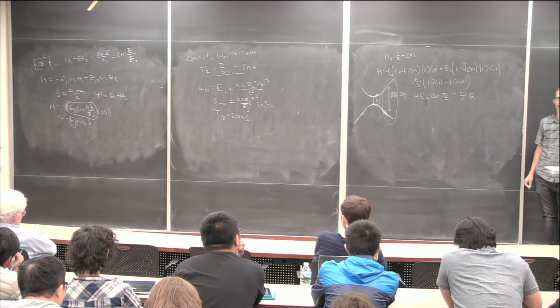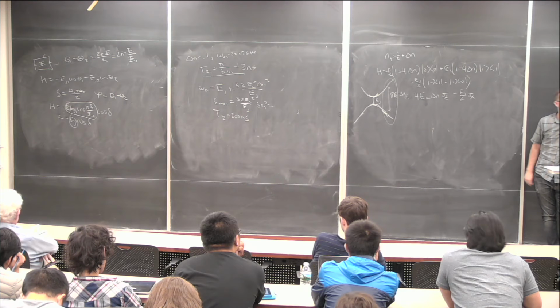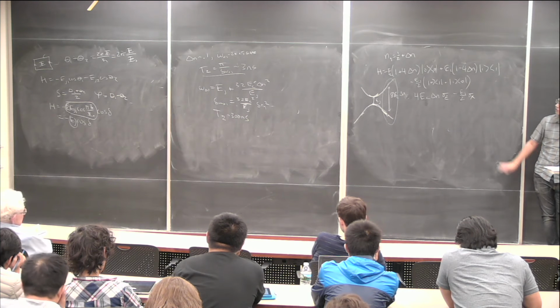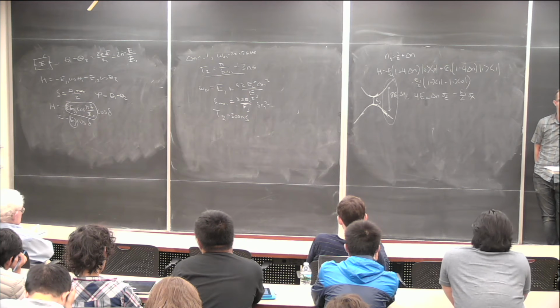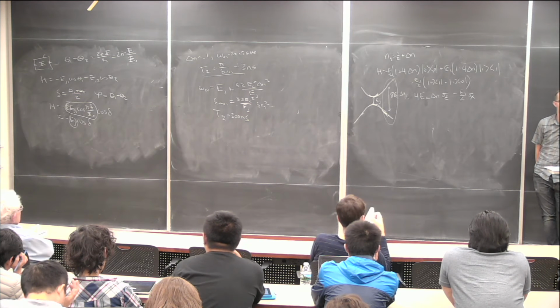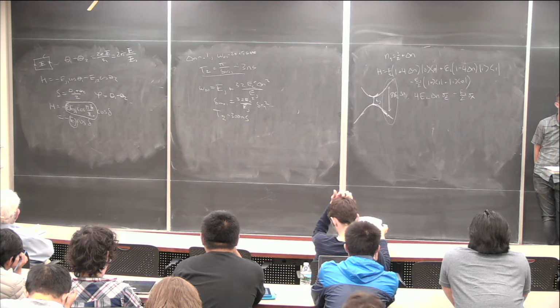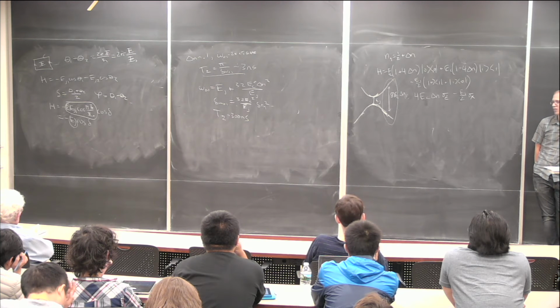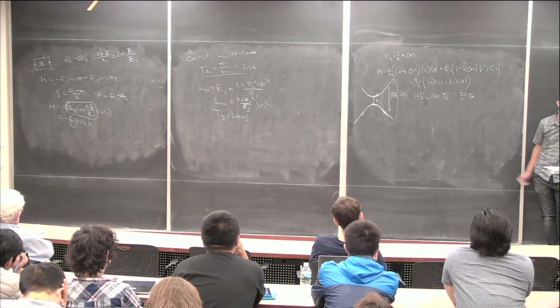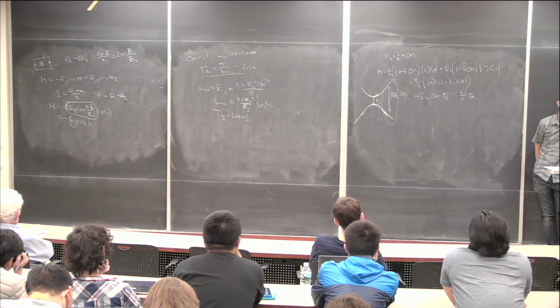And so that means that generally speaking, the T2s you get from flux noise are better on the scale of when we were making these quantronium devices, right? So these quantronium devices were limited by second order fluctuations in charge noise rather than first order fluctuations in magnetic field. Now, in our newest devices, we've really gotten rid of the charge noise effects, and it turns out that they are limited by these flux noises.